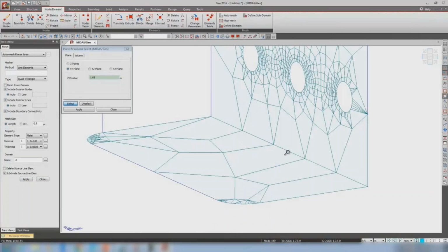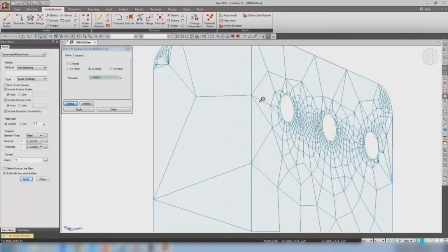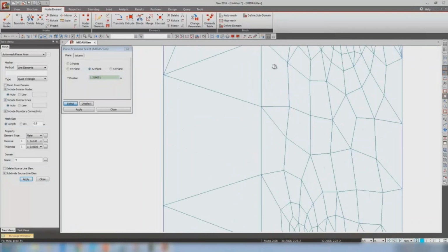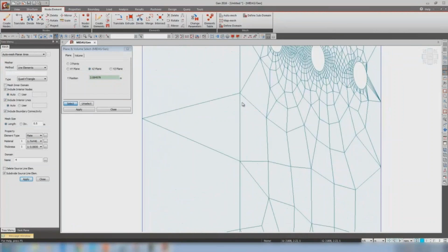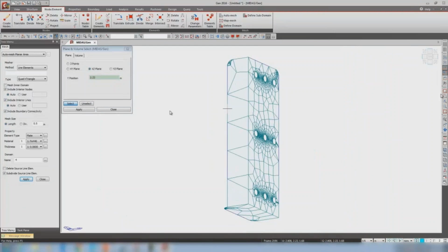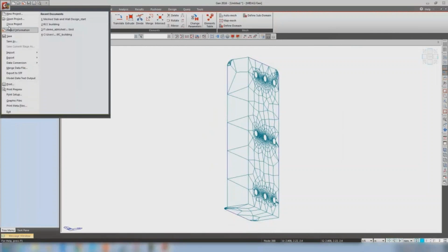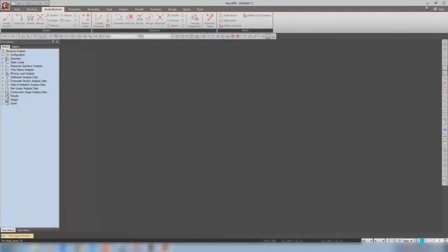See the joint between these two. Everywhere the joints are automatically taken care of. No need to worry about the joints. Similarly for this XZ, I just select this one point, 0.5 and apply. Now all the joints and the entire thing is matching. You can see, so a lot of time you can save in the generation of the meshing. Just one click, within one click you can generate your meshing. No need to go and do the entire thing.